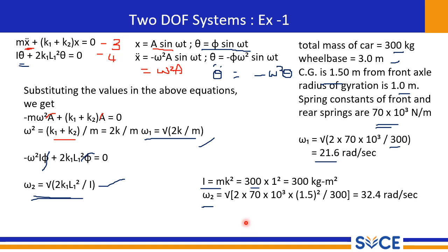This is the way we have to calculate the natural frequency for any given application by simplifying the equations of motion. So we can design and develop any kind of system in such a way that it will avoid resonance when it is excited by external forces.